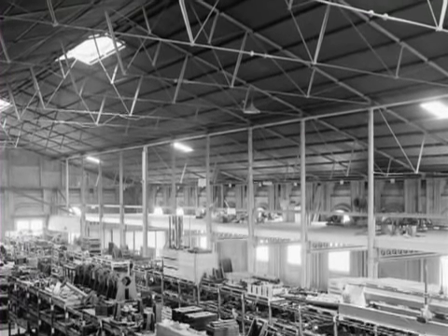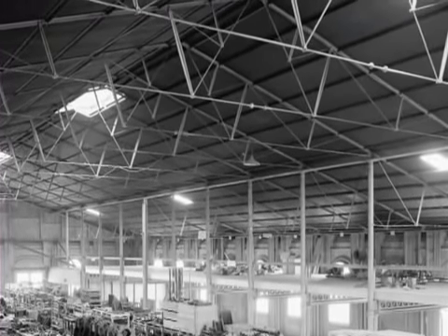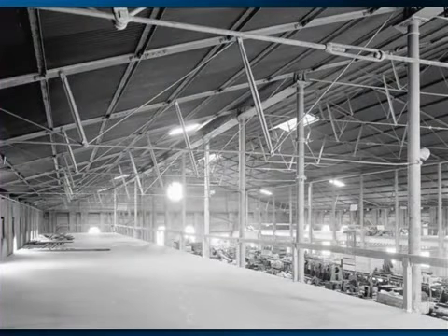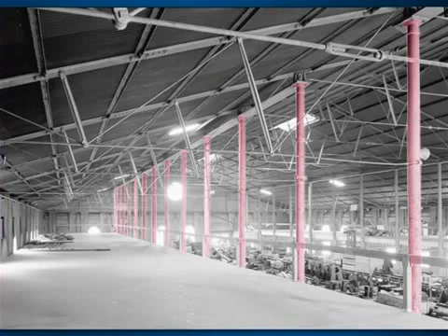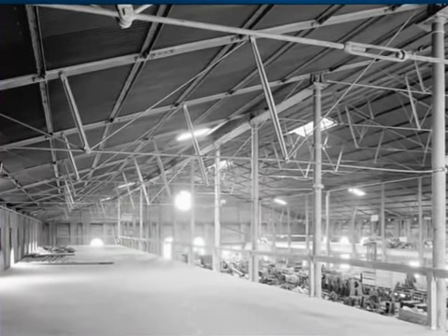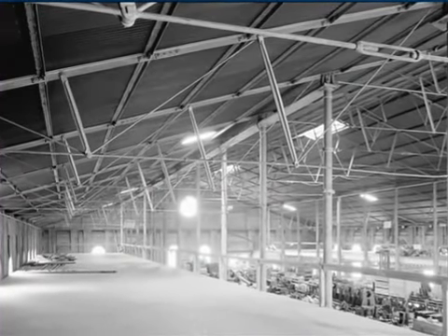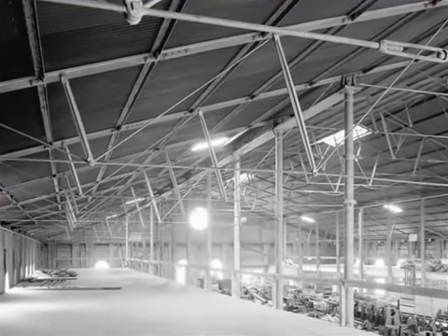I love this building. I love it as an example not only of a historically important early American structure, but also because the interior structure, shown here, is completely visible and it's beautifully configured to communicate how it carries load. And here's an even better view of that internal structure for our purposes, because we want to look at both the roof trusses, where we'll find some compression members, and at the main columns, which are visible on the right-hand side of this photo. For now, recalling that a truss is composed entirely of members that carry load either in compression or tension, can you identify any of the compression members in this truss based solely on their shape?